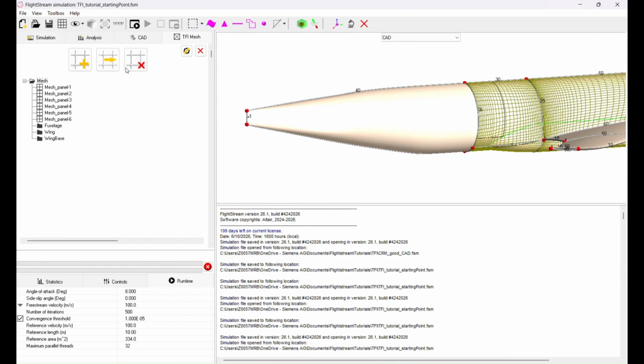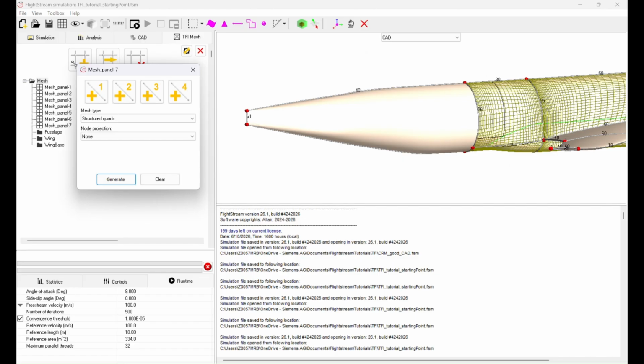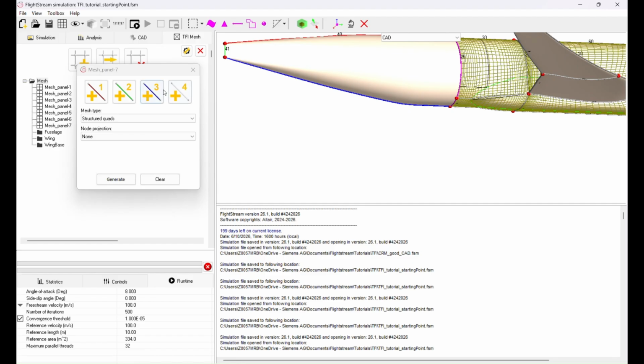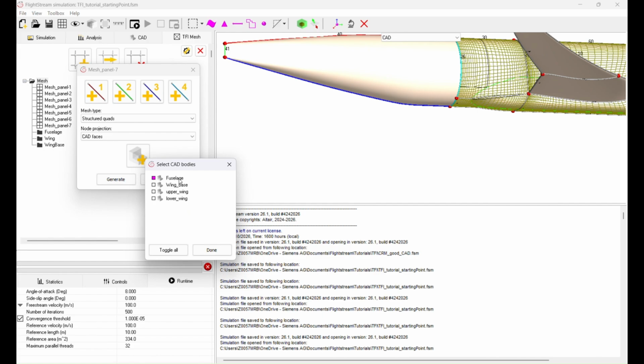Note that we selected our growth rates with proper blending in mind of the mesh. There will be some banding, but as long as the growth rates are kept within an acceptable amount of each other at the points where the panels blend together, the mesh will have no issues with the solver.